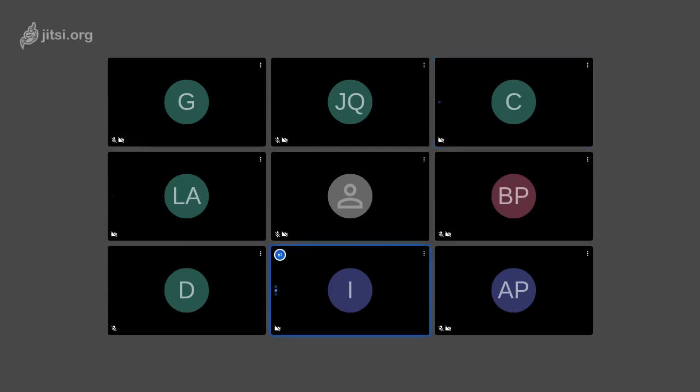There are some issues in general. I mean, let's say in the IFC format, you model in 3D, but typically if you want to do then a finite element model, you have to do what we call the analytical model. So this is one of the challenges: if you have a reference of a 3D model and you want to define the analytical model, either you have to do it manually or you have to create some algorithms that will give you the analytical model.